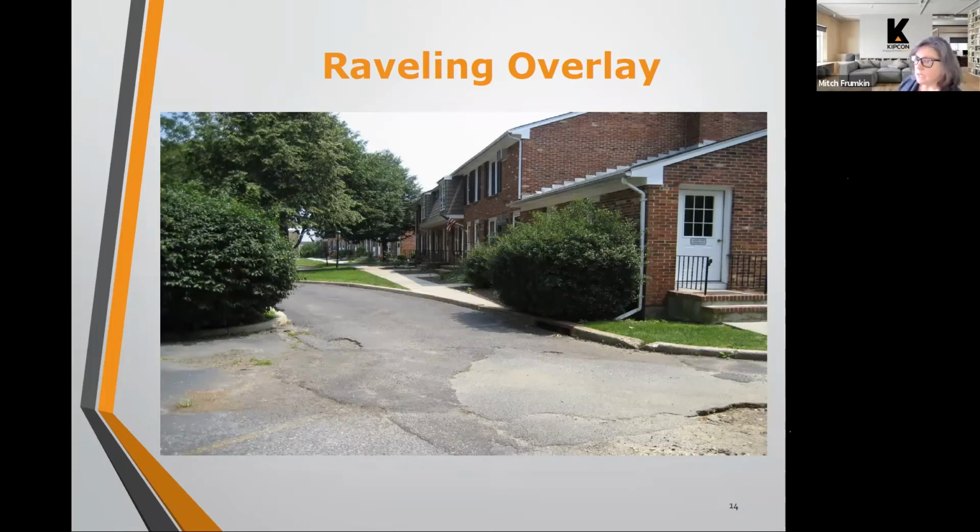to identify areas where the curb is in disrepair and may need to be replaced. In the case of Belgian block curb, it may just be a matter of resetting block that has been knocked loose by plows or people driving over it. But with concrete curb, the whole curb section typically needs to be removed and replaced. And that needs to be included in a pavement project. So we will quantify that amount of curb and put it in the base bid for replacement.